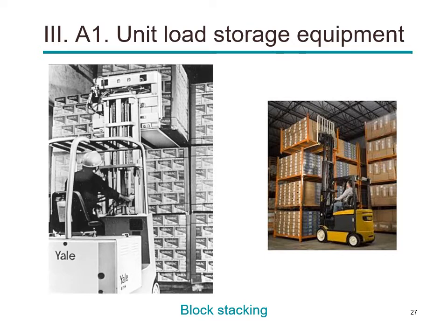This is an example of block stacking. You see these are the loads, and these loads are placed on these stacking blocks so that you can put them on top of each other using a forklift, and you save space this way. So if you stack all these cartons on top of each other, after some weight, after some number of loads, the bottom ones will be damaged. So in order to avoid that, you can divide them into certain allowable numbers, and then you can stack them using these block stacking systems.